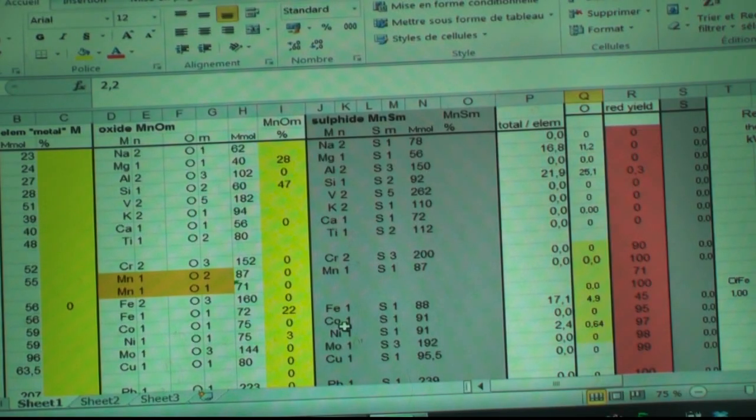And here I must say something. Actually, of course, the ore contains Fe2O3 and not FeO. But since before the SAF you have a kiln with preheating and using coal, at low temperature this is reduced to FeO.